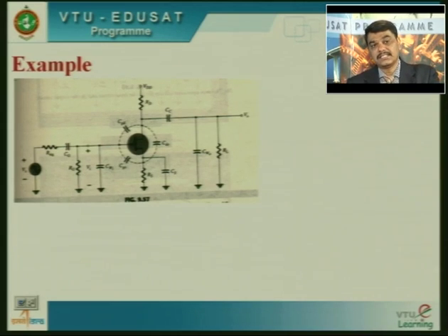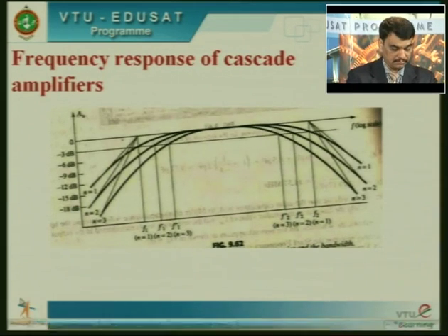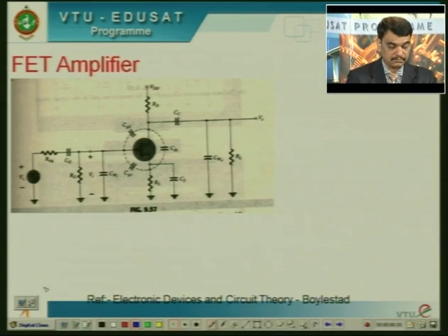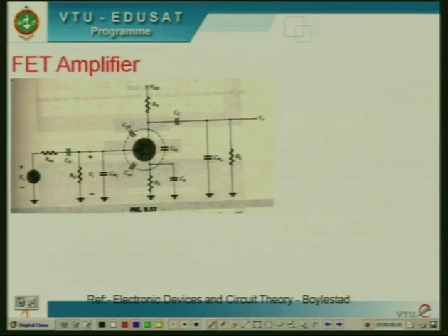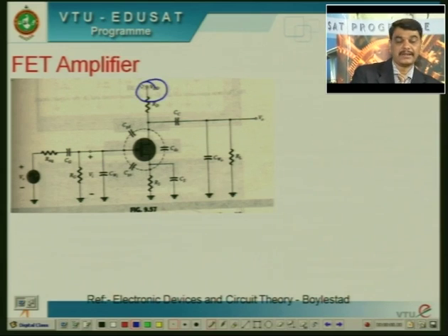For the AC analysis, normally the source DC voltage is not applied. This VDD is used to determine only the DC analysis. For this circuit analysis, we need to find the AC response. Therefore, we are not using this VDD for this problem.